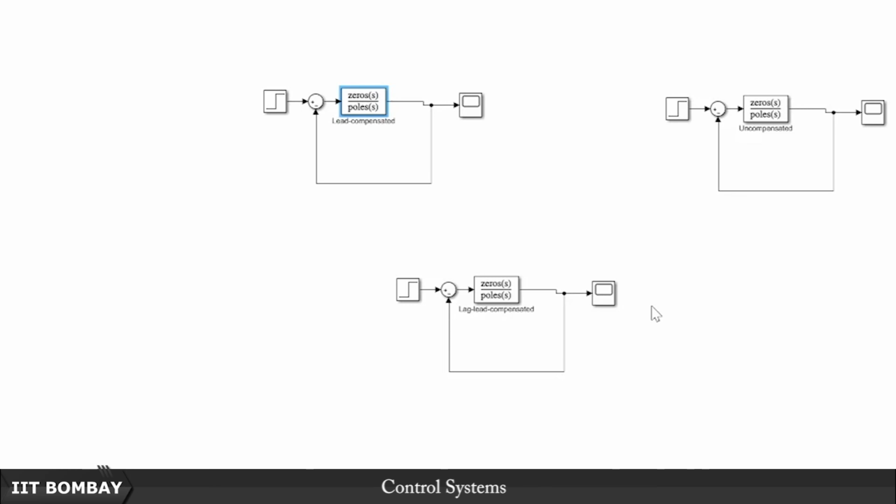I used my discretion at 2 junctures particularly. The first such point was when I chose where to place the lead compensator's 0, and the second where to place the lag compensator's pole. Those two are subjective choices. So you can try out the same system with different choices and see the difference for yourself.